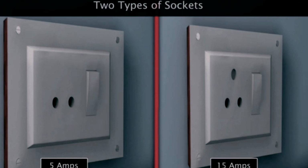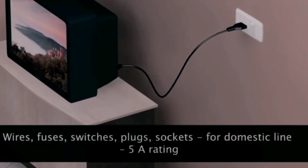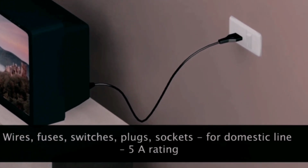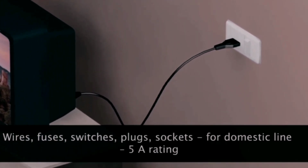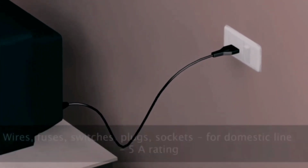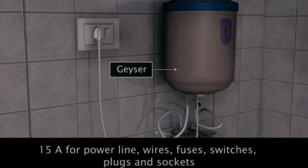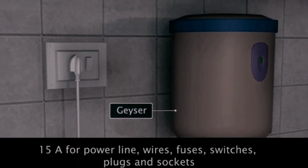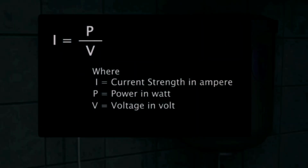Generally, there are two types of sockets used in domestic and power lines. They are 5 ampere and 15 ampere. Power cables for heaters, fans, TVs and washing machines are connected to 5 amp sockets in domestic lines. Plugs of geyser and air conditioner are connected to 15 amp sockets in power line. We can use the equation shown to select the type of fuse and cable for an electrical appliance.